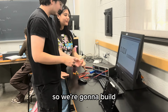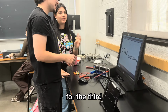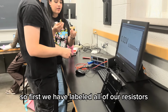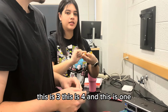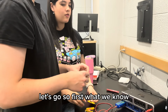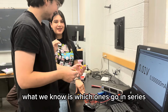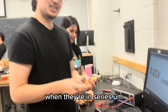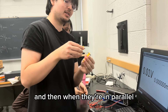So we're going to build the circuit to figure out the voltage and current for the third resistor. First, we have labeled all of our resistors. This one's resistor 2, this is 3, this is 4, and this is 1. First, what we know is which ones go in series and which ones go in parallel. When they're in series, you add them like this, and when they're in parallel, you add them like this.